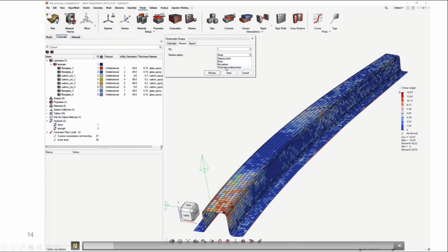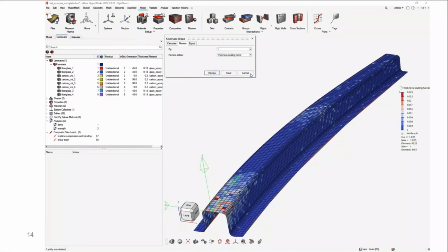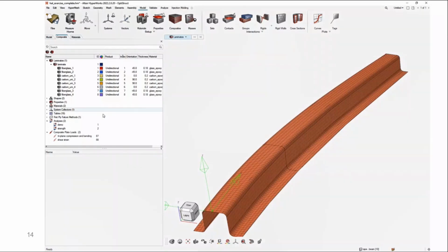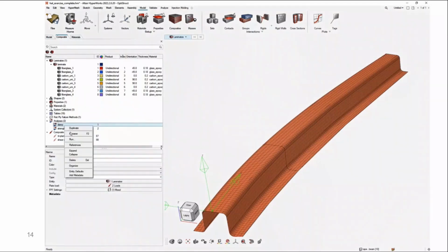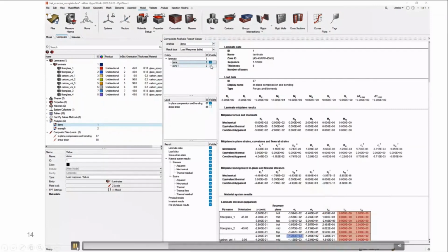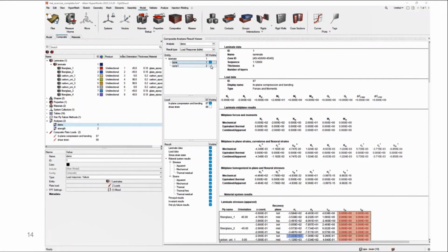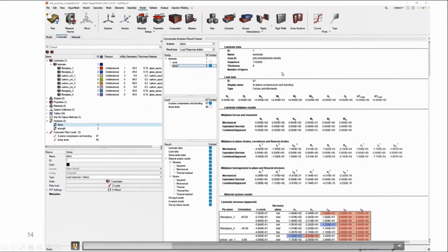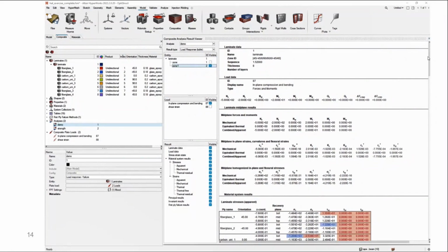I'm also quickly reviewing the thickness scaling factor, because that is also something that was enabled just recently. Now we can look at the original calculation, meaning we're doing just the element or laminate-based analysis. Our laminate has two zones on our head here, and we can see the laminate being plus minus 45, twice 0, minus plus 45. So that's one bit of this complete laminate here, and also the complete one in the second step.